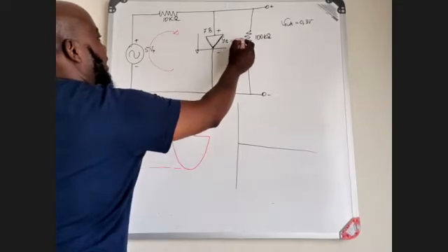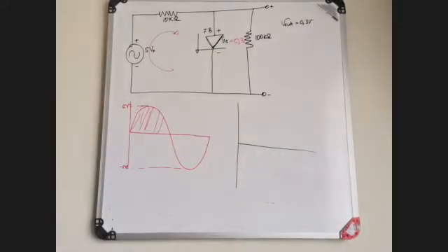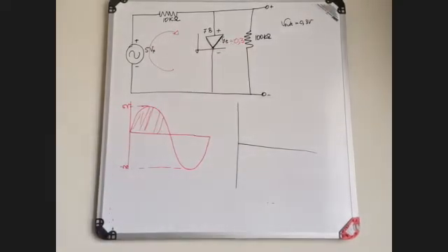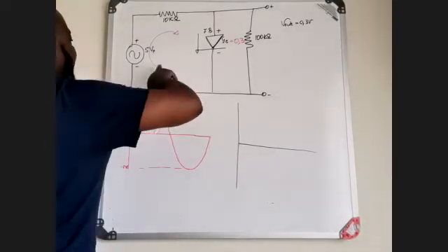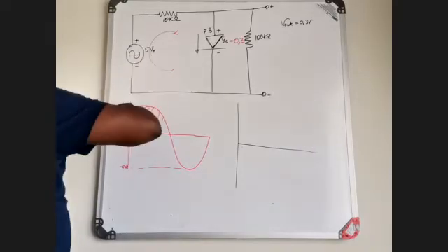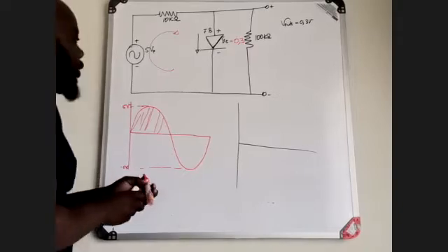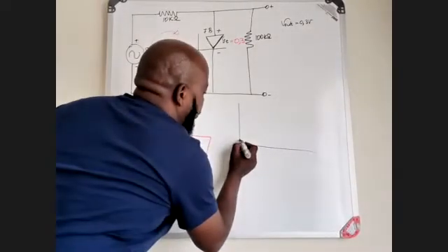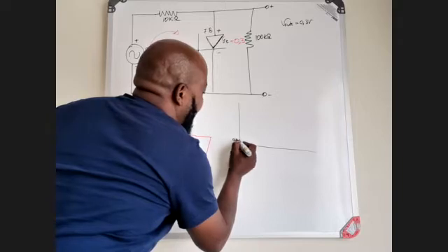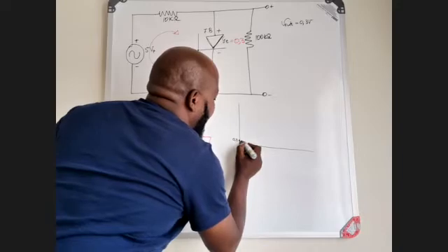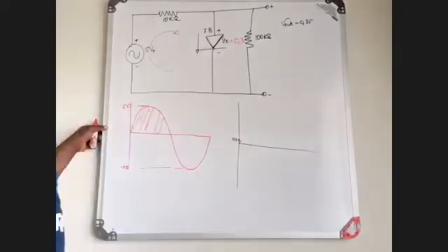And you will see that it will only get to be switched on at 0.3 volts. Then you will allow the current to flow. So you will keep on increasing this voltage, but that voltage there will never increase; it will stay the same. You can increase this voltage as much as you want up until the maximum voltage, but that one will remain at 0.3 volts.